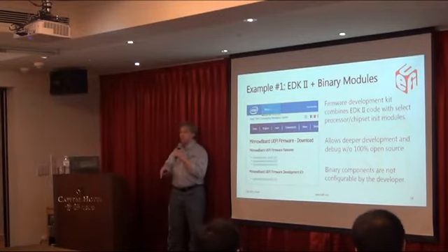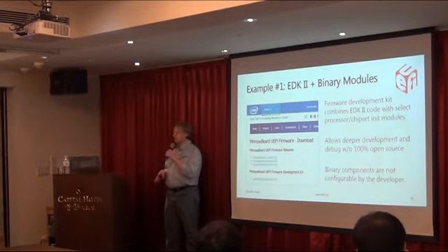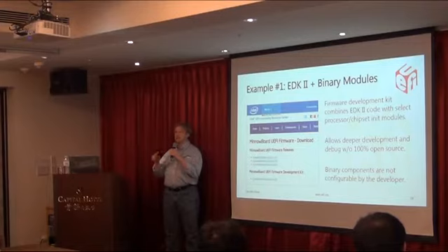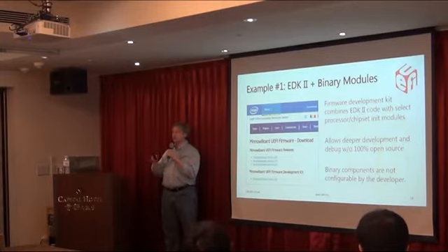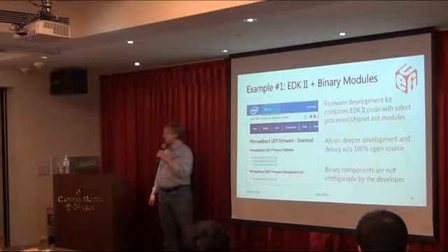So again, we do have a project for the Minnow boards that uses this EDK2 plus binary kind of combination. In my opinion, it's not the cleanest way to do it because it's very board specific which components get locked up in these containers. So from a debugging exercise, if you want to understand how the boot works, it's not as transparent, but you can still turn on the open source components and do all of that yourself.